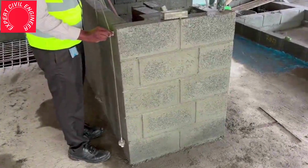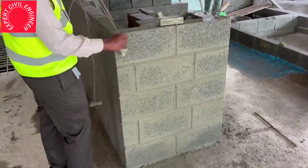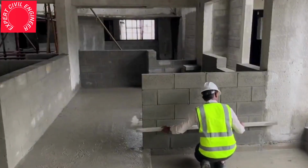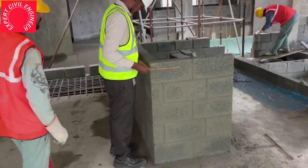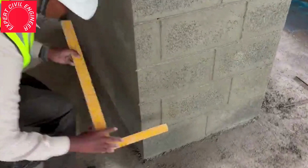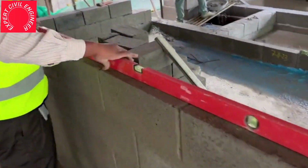After raising the blockwork to a height of 1 meter, conscientiously verify the vertical using a plumb bob for optimal stability. For optimal precision and alignment, regularly cross-check the blockwork using an aluminum straightedge to ensure it sits flush against the column surface. Position the aluminum straightedge horizontally across the blockwork, resting one end against the column surface.